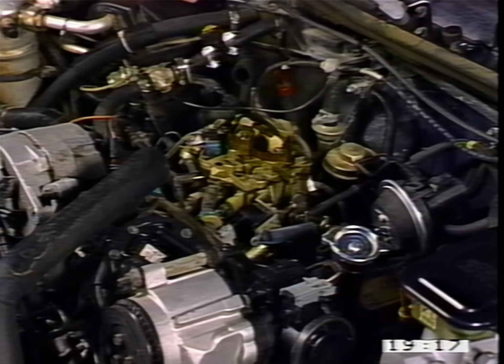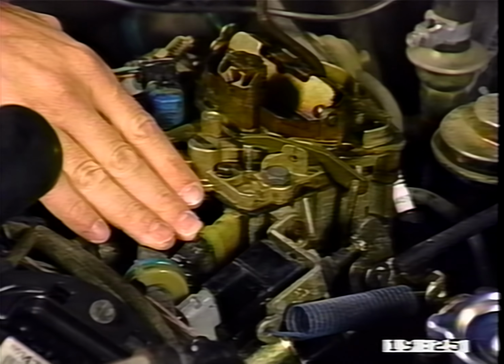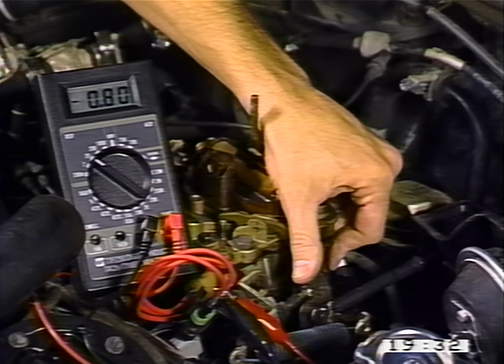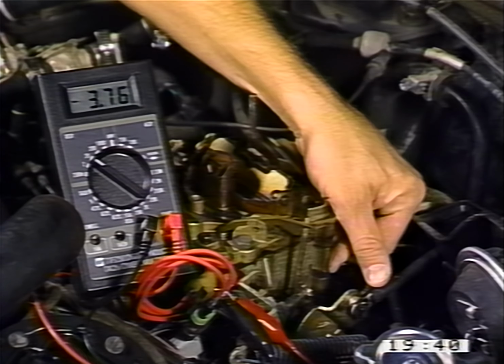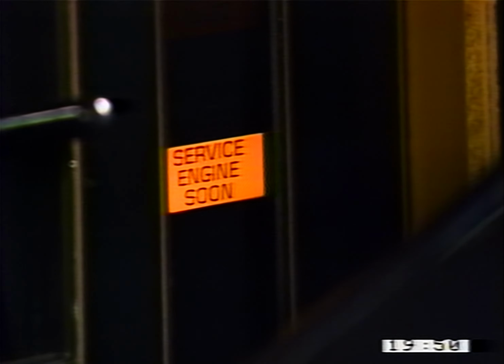Throttle position sensor designs vary depending either on carburetor or fuel injection application. The TPS is found mounted either in the float bowl on carbureted applications or on the throttle plate of fuel-injected systems. It's supplied with a 5-volt reference, signal return, and ground lead. The signal on the return lead starts at about 1/2 volt at idle and increases smoothly as the throttle is slowly opened. There will be a wide range of drivability problems if the TPS signal is erratic in any way. TPS problems are identified with a code 21.